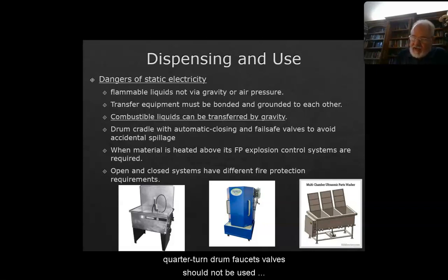Quarter-turn drum faucets, valves, should not be used when dispensing combustible liquids or other hazardous materials from 55-gallon drums and drum cradles. Inspection should ensure correct equipment classification and no cooking or heating appliances nearby. When processes require heating of flammable or combustible materials above their flash points, Fire Prevention Code require additional special considerations for safety distances to adjoining properties, as well as an increased level of fire resistance of the structure.